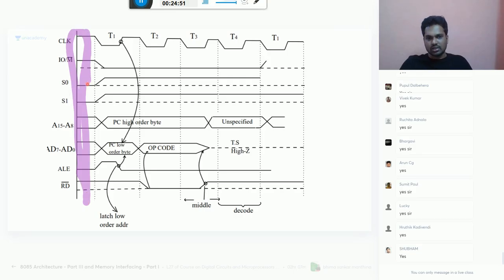Start from here. Okay, this is your clock. This is your clock, because when you are calculating time, it will always be shown like this in digital. I have discussed this already. For delays and calculations, we take the middle point as the reference. I also told you that point when we discussed the propagation delay concept. Now come here. Opcode fetch is a memory operation.